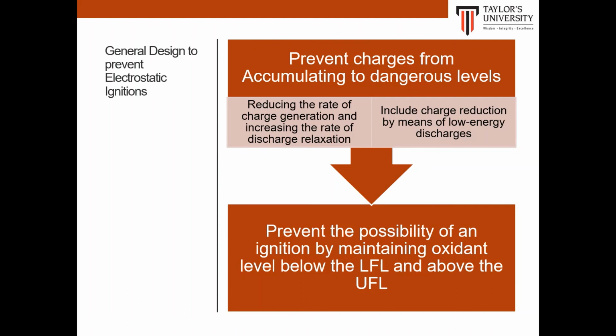But when a dangerous discharge cannot be eliminated, then it is important to prevent the possibility of ignition by maintaining the oxidant level below the combustible level, by inerting, or by maintaining the fuel level below the LFL or above the UFL.